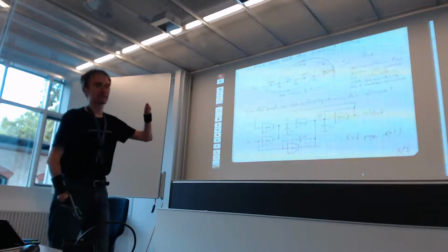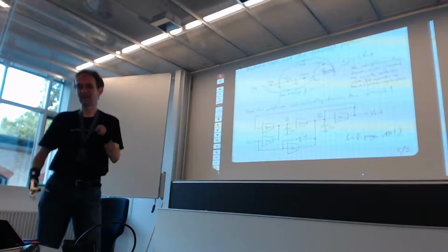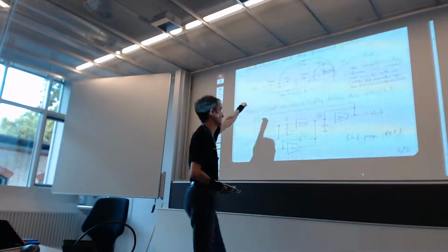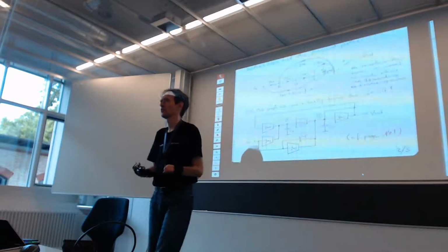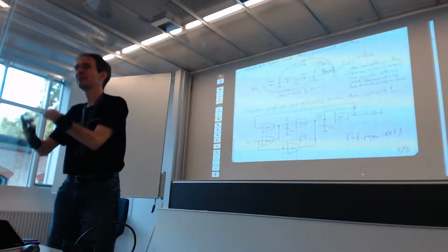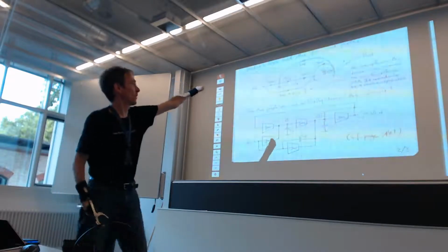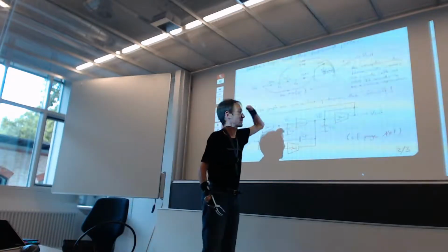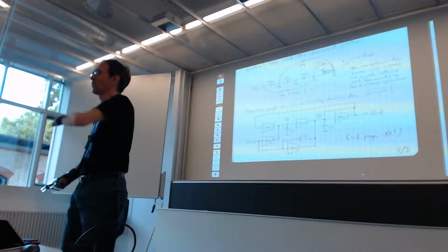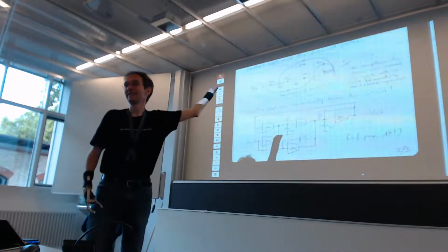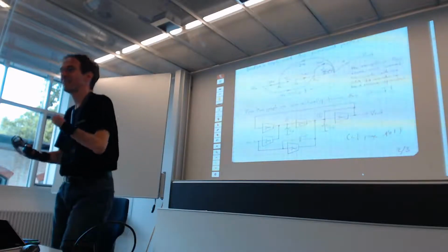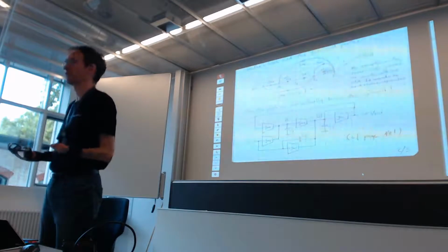But that's not the point. That's an implementation question for later. The point here is that if you have understood what it means to scale a node variable, you can say, I want V1. Presently, if I calculate it, I will get voltages of 10 volts, and my maximum voltage is 1 volt. I say, take 1/10 of that, please. And then you still have the same Mason rule, the same transfer functions.